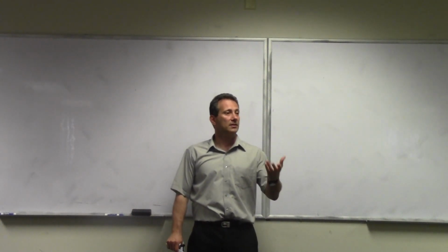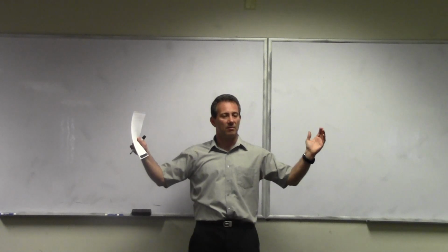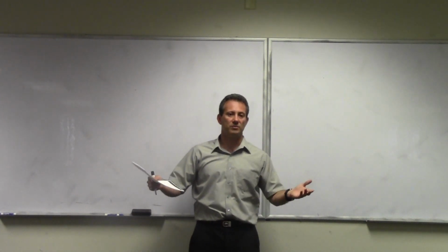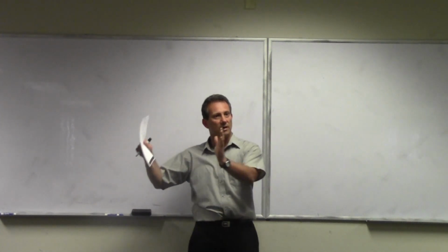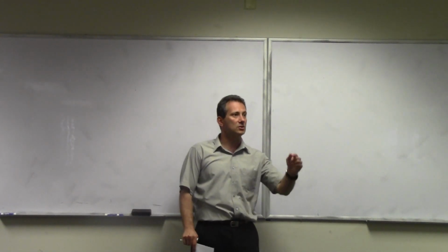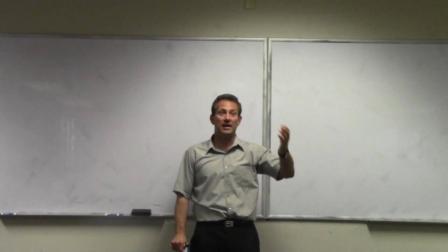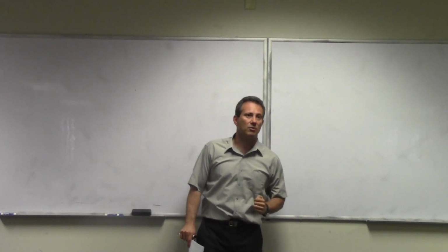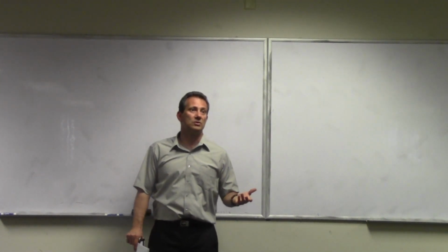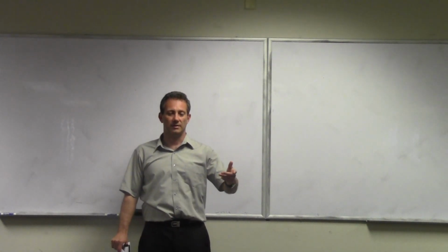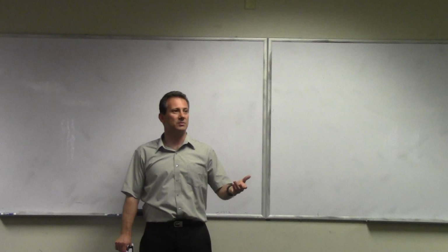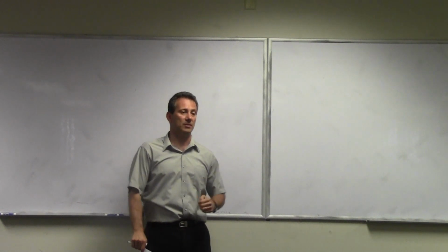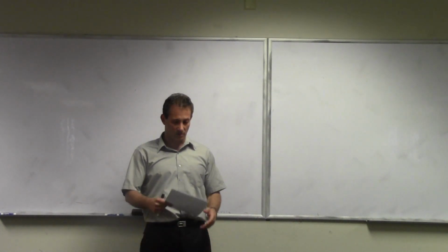And this is multiple access, right? Let's say you have multiple communications sharing the same channel. The most basic way to do that is to give a portion of the channel in the frequency domain to each one of the communications. And that's our FDMA access. In FDMA, you say, okay, my communication is just going to use this portion of the spectrum. A lot of systems use FDMA, actually all wireless systems are FDMA to begin with, because they all operate in a certain portion of the spectrum. And then also we have FDMA on landline channels as well.